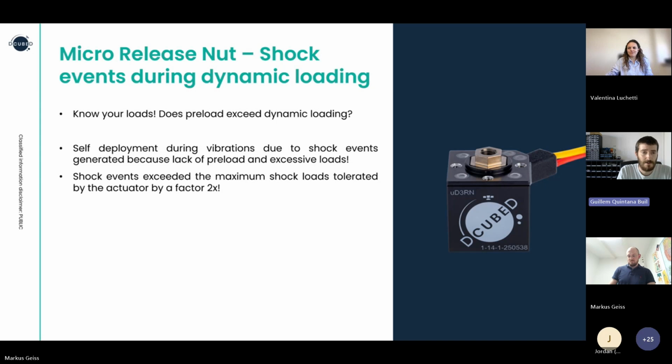In those scenarios, the payloads themselves will start gapping, and this is going to generate some shock events. Depending on the design itself, the materials employed, the magnitude, or the difference between the preload and the dynamic loading, this can generate a massive amount of energy. So it's something really to keep in mind.